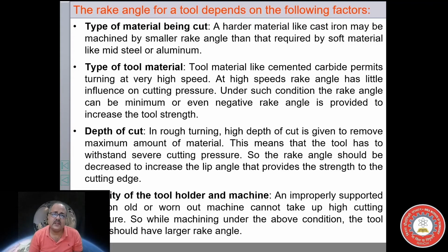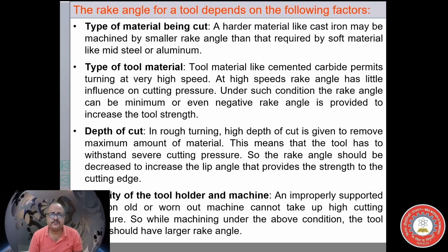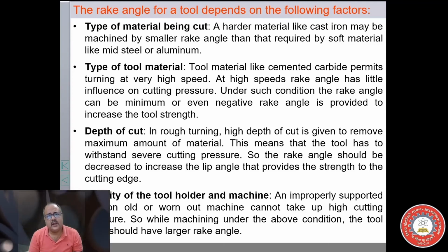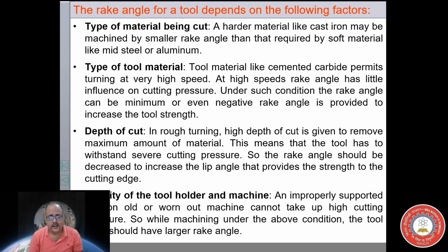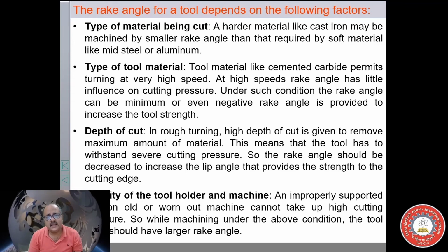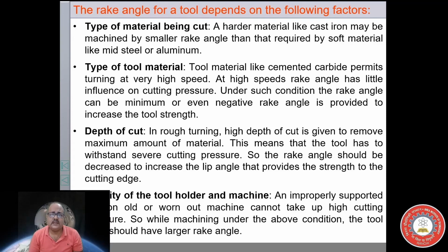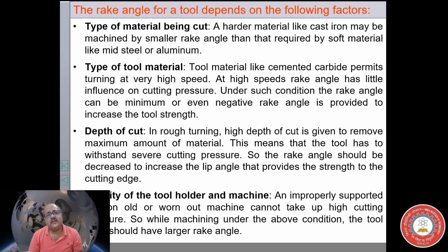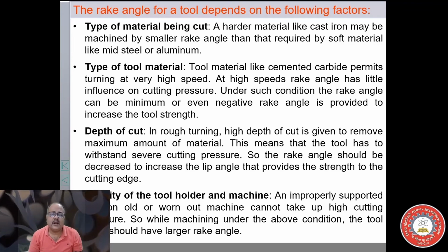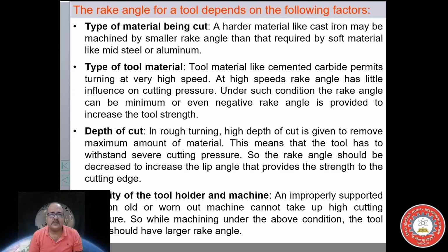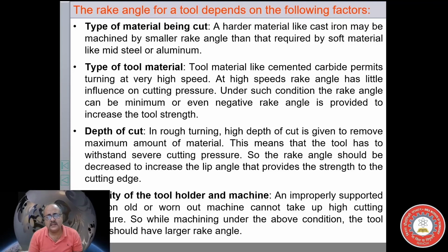And one more thing, as I have said, if you keep on increasing the rake angle, there is a video on it. You can go through the video. If you keep on increasing the rake angle, the cutting power that is required will decrease. Now then, at what point should you stop? Experimentation has been done, and it has been seen that if you keep on increasing, the cutting force required decreases. But after a certain angle, the cutting force does not decrease much, whereas the strength of the tool reduces significantly. Therefore, normally we keep the rake angle around 10 degree to 25 degree max.